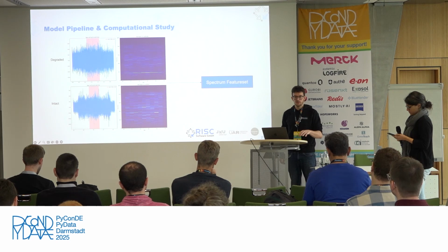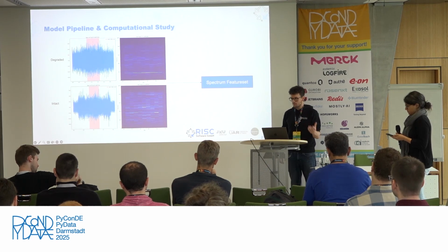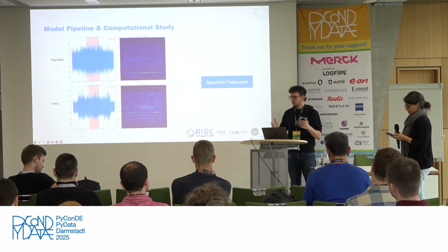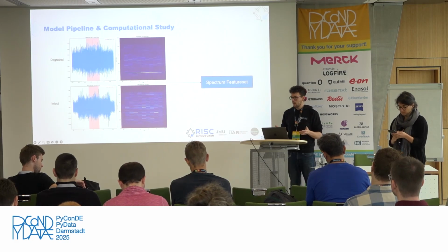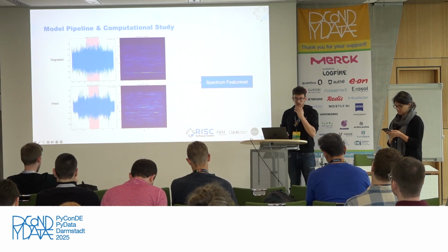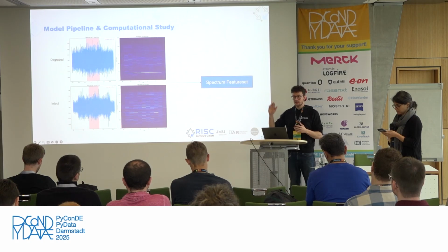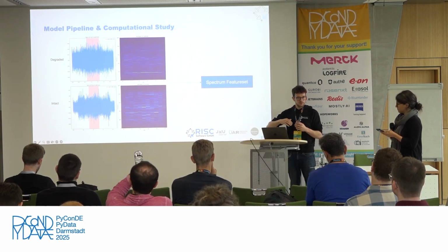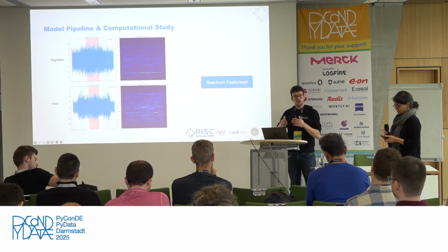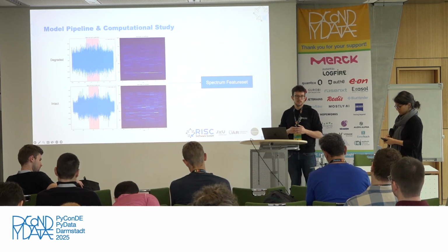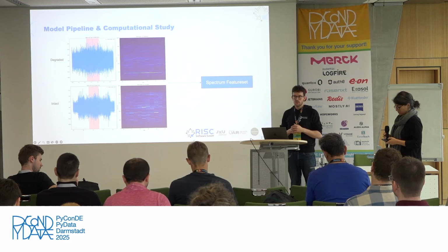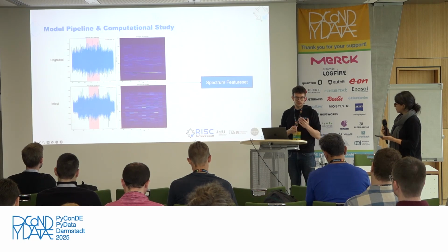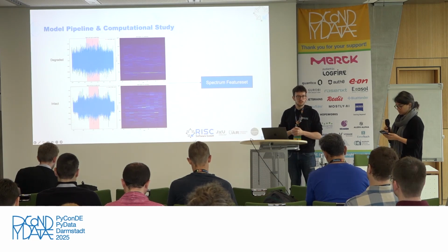So you measure waves which are propagating through a body. That can be any machine or table or anything else. Those are interesting because if you have a process, like where we produce a flame, you automatically have some vibrations stemming from this process. And these vibrations are what we measure here on the left side. And the sensor is a very high-frequency sensor. So per second, we get around 20K samples. And that's the main idea here.